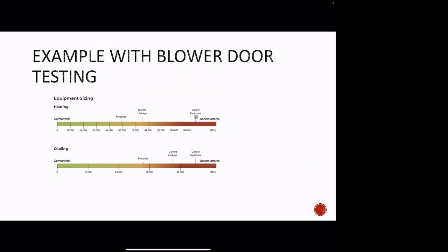135,000 BTU furnace. With actually measuring the blower door number, which I said earlier is the most important number to have, I'm able to true it up to their energy consumption, perform a proper engineering analysis, and show what size furnace they should have with their current leakage. So even though they got a 135,000 BTU furnace in this house, they only need an 80. If they air seal, we can actually get away with a 60. And this is on a 3,000 square foot home.